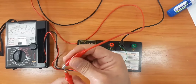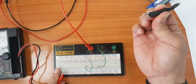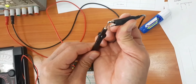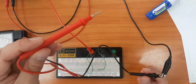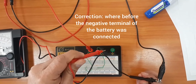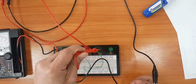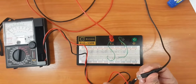Or in any manner, you can cut also the negative terminal of the battery and connect it to the negative test probe of the multimeter and connect the positive test probe to the resistor where before the positive terminal of the battery was connected. Okay? So as you can see in my demonstration, it is like this.